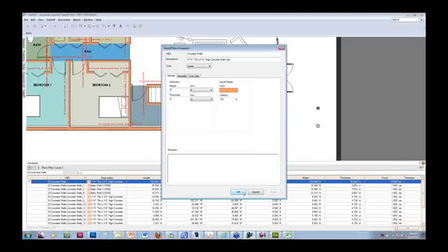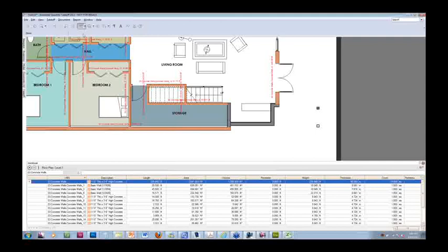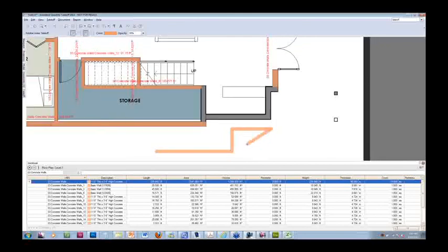So now, watch. Even though I'm not picking it from the model, I can just draw an individual line, using this tool for polyline. Let me just pick the one here. I can start drawing a line, and not single click, this is the one. You have the different polyline linear takeoff. If I start drawing, notice that it has a 6-inch thickness, and even though it doesn't have a height, it will have that 9 feet high that is already preset. And it has the color that I told it to have originally. So you have all these different options, so I can start drawing my shape.